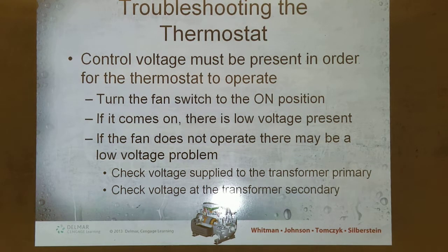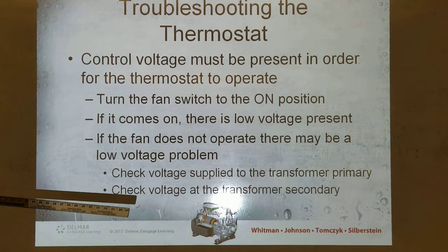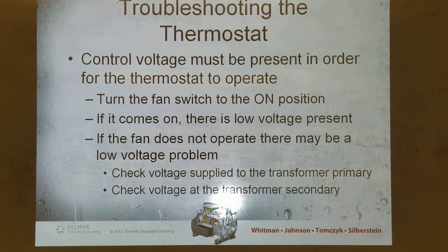So by process of elimination, that's all you're doing when you troubleshoot. Okay, you get that? You're just eliminating things that it can't be. So if you go in there and check the thermostat, and you hear the fan come on, you're not going to go check the transformer, because you already know it's good, it's running, it's got control voltage, right? So all you're doing is eliminating things that it can't be. Makes sense. It's not that difficult.